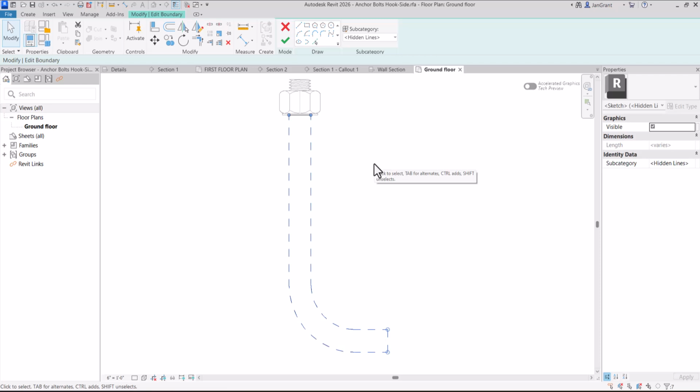But this is another learning tool to say that you can double click on a family and change it. Now, if you are going to change it, you really should save it as a different name. So you double click to open up the one that you are already in. But if you save it, the changes are going to be back in all of them, right? So it's up to you. But I hope that's pretty clear, where if you save it as a different name, you're creating kind of a different family. And then you're not messing up the original one, right?